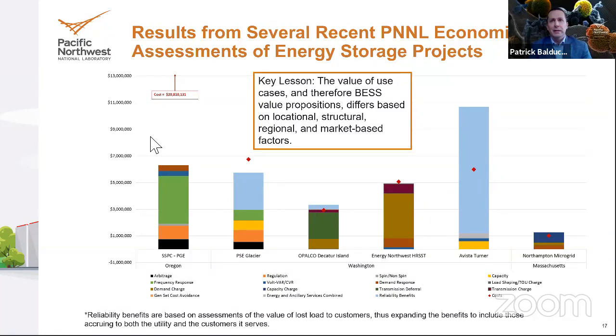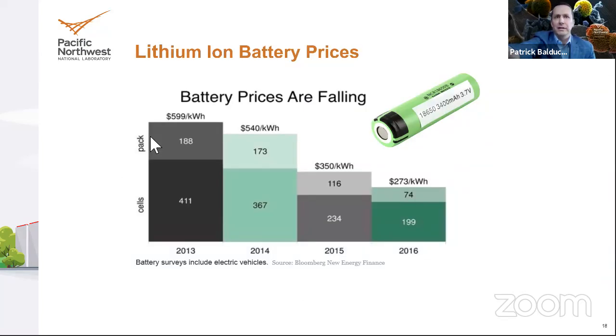At Schweitzer Engineering Laboratories, they experienced voltage sags throughout the year, and the ability of the energy storage system to detect those voltage sags and address them before their machine shut off generates a benefit that's measured at about $150,000 per hour of downtime that's avoided. And every time the machine shut off, it takes them at least 3 hours to come back online. So each year, the energy storage system could help SEL avoid basically a $450,000 to $500,000 cost. So an enormous benefit there.